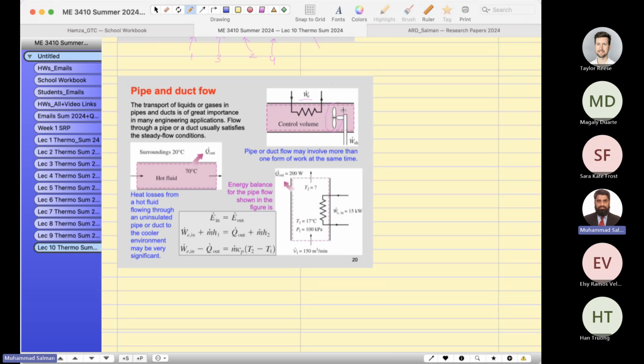We have a big blower, and we have some furnace, a gas furnace. So what happens in the winter? We use this system. In the summer, we use the same as refrigeration coils, evaporator coils, and the same blower is used to pass the air through the HVAC coils, the evaporator coils.